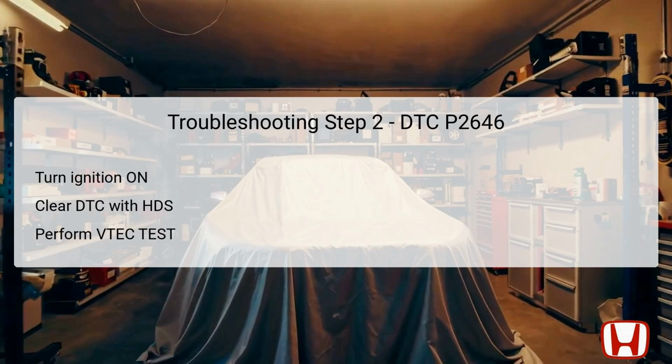After ensuring the oil level is correct, the next step involves verifying the problem using the Honda Diagnostic System, or HDS. First, ensure the vehicle is in the on mode, allowing access to the vehicle's onboard diagnostic capabilities. During this process, you'll clear the recorded DTC from the system using HDS to reset the vehicle's diagnostics. Following that, perform the VTEC test located in the inspection menu of the HDS. This test will help determine whether the system can operate under normal conditions.